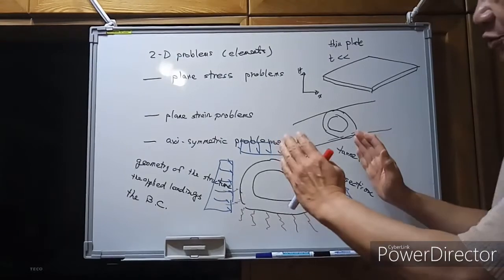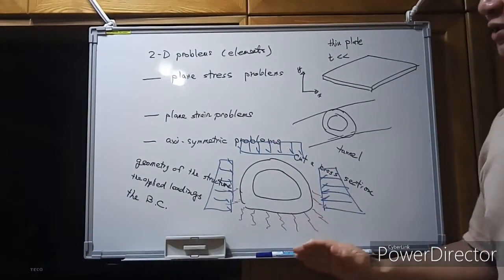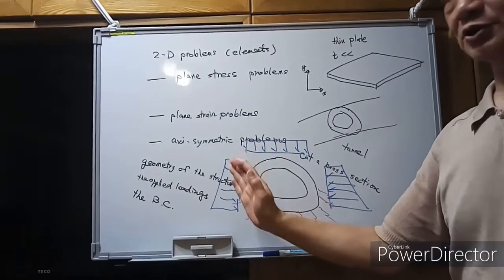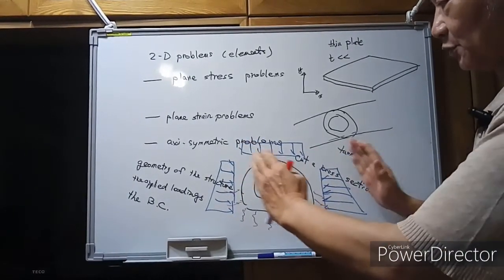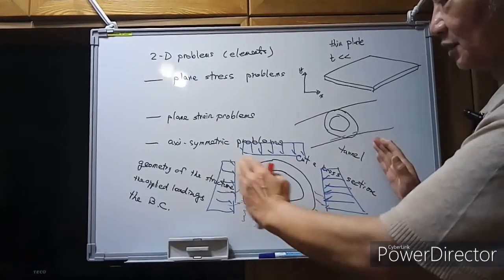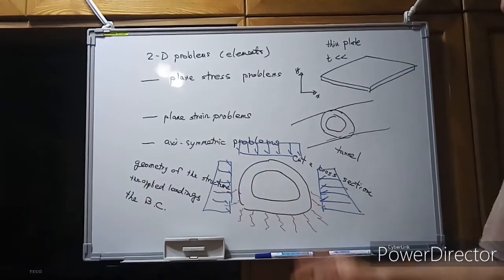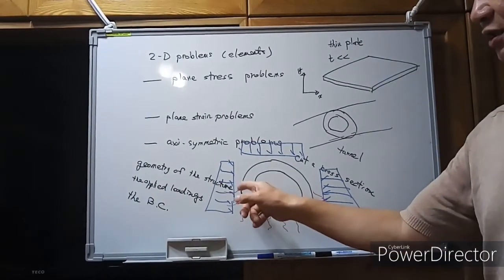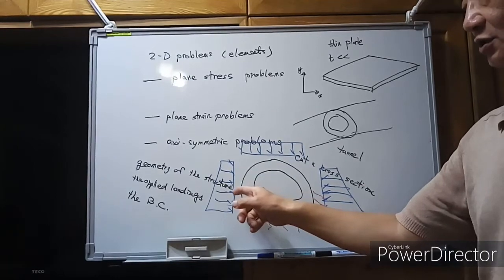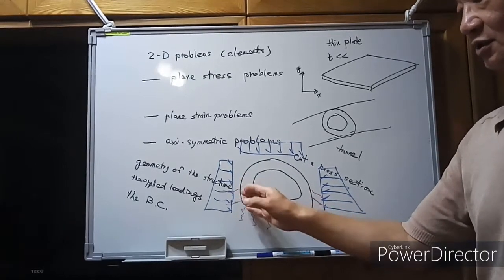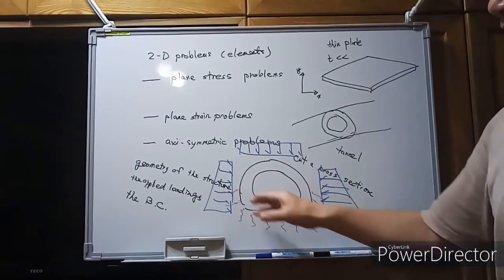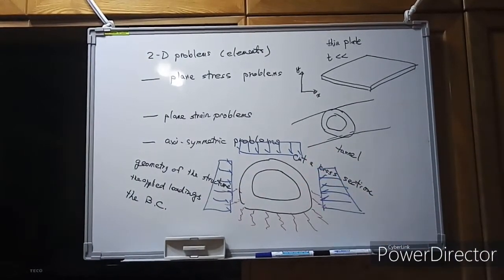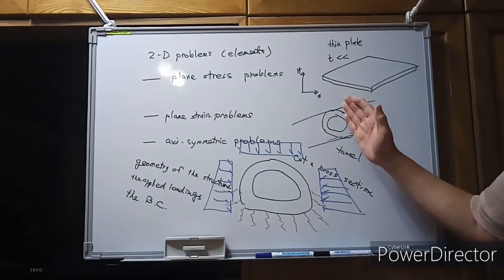We have the lateral pressures, either from the soils or from the water, applied to the left and the right. And the boundary conditions can be assumed as distributed spring supports around the bottom half of the tunnel.